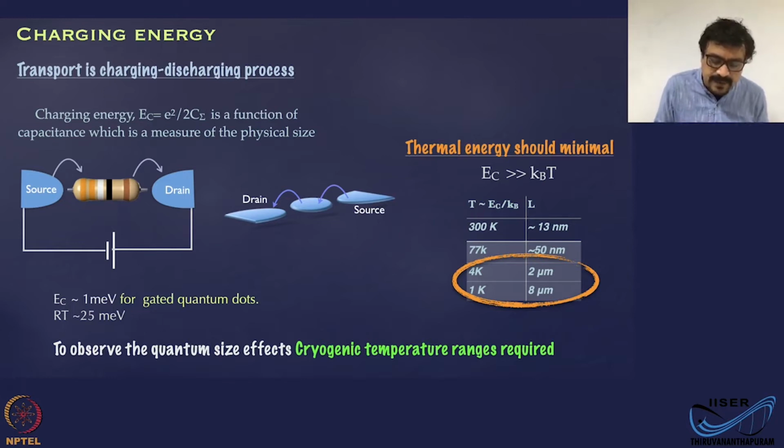Now, you have a source and drain region here. Assume that you are going to put an electron through a thin tunnel region, a really thin insulating region, where you are going to add electrons and remove electrons from the other side. What I am trying to say here is that it is not connected completely with a metal. There is a small region which allows you to put electrons easily, but it is a non-conducting region. The electrons tunnel through this thin insulating region which separates the source or drain from the device.